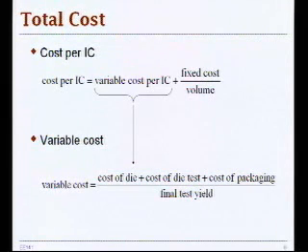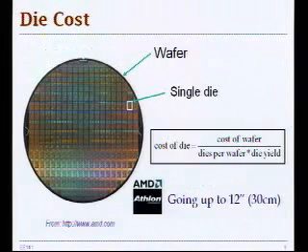So in addition to that test yield, we also introduced the quantity die yield. And that has to do with the die cost, where cost of a die is directly proportional to the cost of a wafer that you use to fabricate your design. The wafer has a number of identical dies distributed all over the wafer, and that was inversely proportional to the number of dies per wafer and the die yield.